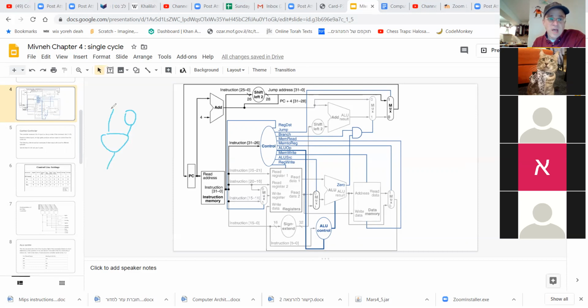So now this line, whether it's a 1 or a 0 on this line, whatever it is, I'm going to get a 0 over here, because that's an AND. And you just do that with all of the ones that you don't care about. On each one, I go to a little AND and I block them out.